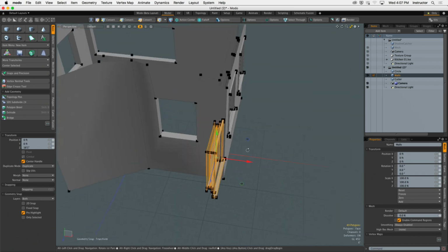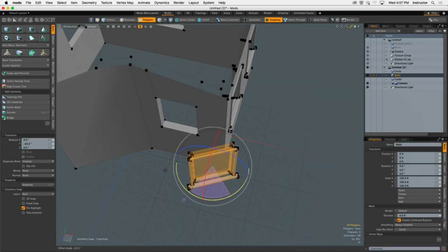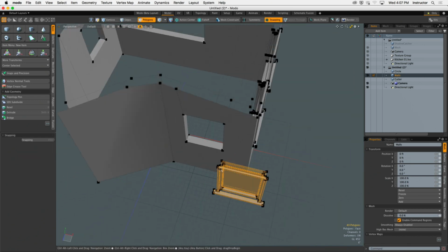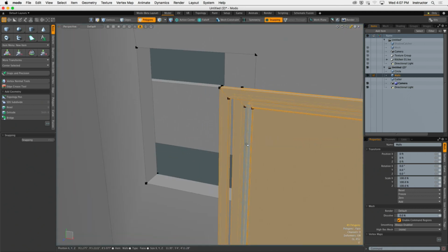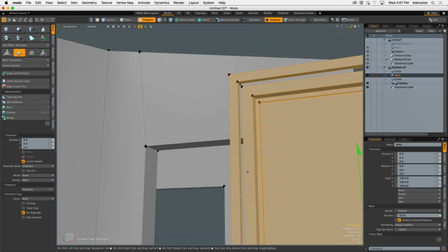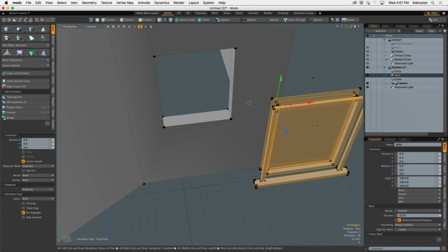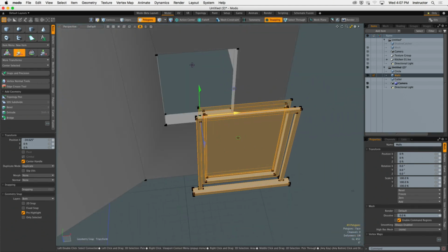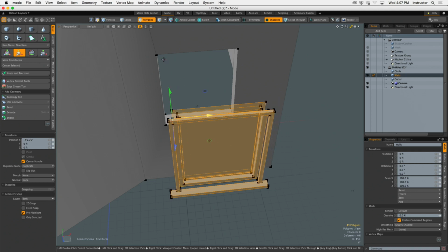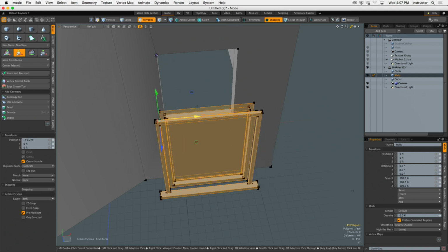Make a copy. This one I have to rotate. Hold down Control to rotate it 90 degrees. Let's do the exact same thing again. Fire off the Move tool. With my snap enabled, I'm going to put it in that corner because that one I can see real easily. I'll put my cursor, see my cursor above over here? Boom, it just snaps. So now I know that it's positioned correctly along the x-axis.